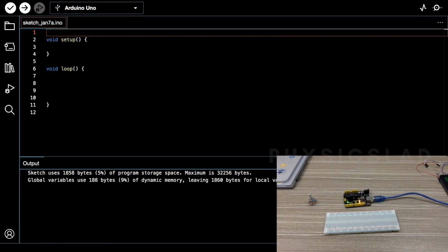In this tutorial, we're going to be looking at how we can use analog reads to control output devices. Analog reads can be anything from your humidity sensor to your pH sensor to your temperature sensor, essentially any sensor that you need a range for. The reason why we can't use digital pins is because the Arduino can record values from 0 to 5 volts, whereas your digital inputs can either be 1 or 0. So not a lot of sensors do 1 or 0. If it does 1 or 0, we most of the time just call it a switch.